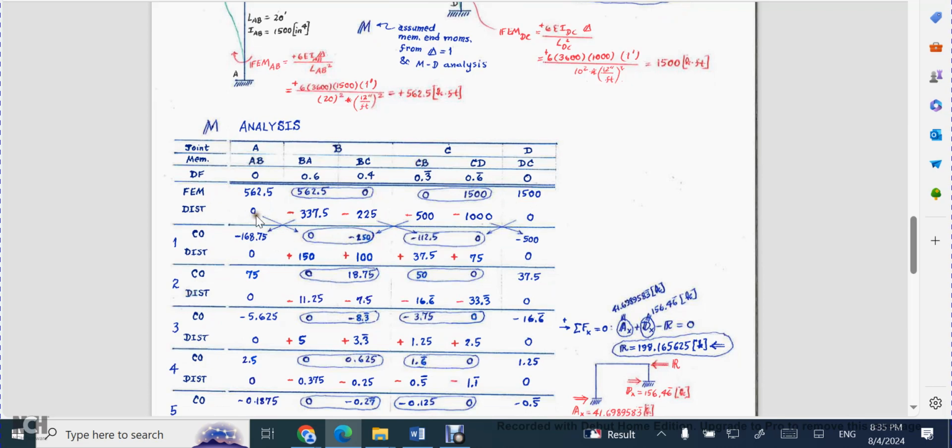I'll just quickly remind us how that went. So you have your fixed end moments. Now you're going to do your distributions as per these distribution factors. And I've encircled the imbalance that exists at joint B, for example, and at joint C, moments-wise. And so you have a negative 250 kip feet of imbalanced moment at joint B. You unlock joint B. You impose a positive 250.